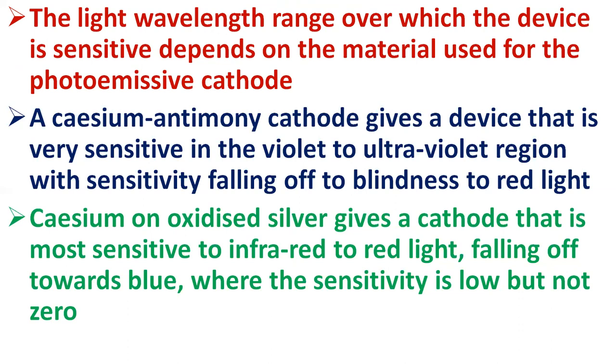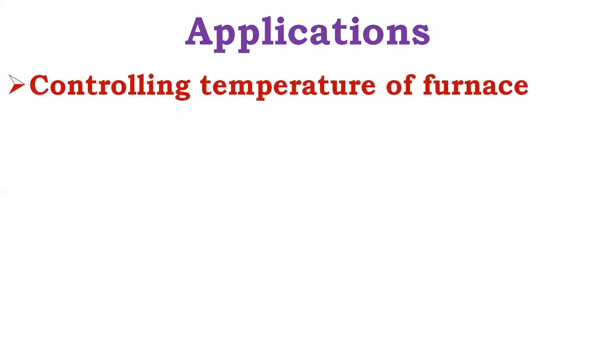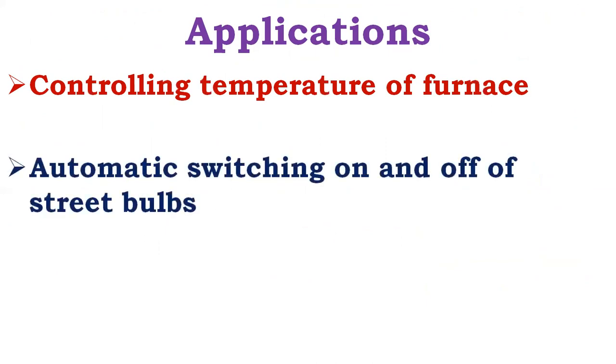Vacuum devices have a near constant anode current for a given level of illumination relative to anode voltage. Gas-filled devices are more sensitive, but the frequency response to modulated illumination falls off at lower frequencies compared to the vacuum devices. The frequency response of vacuum tubes is generally limited by the transit time of the electrons from cathode to anode.